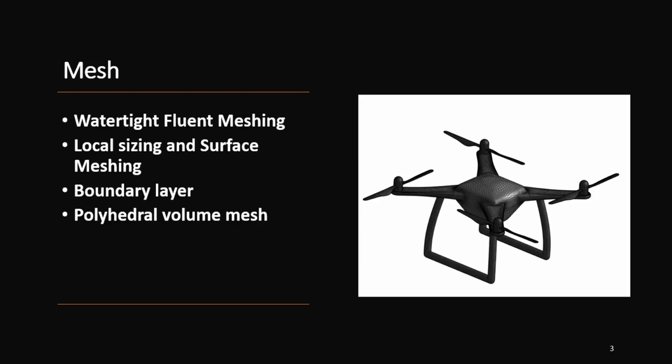You can launch Fluent Meshing in two ways. You can start from SpaceClaim, which we covered in the previous part of the video series, or you can launch Fluent Meshing in a standalone mode. To launch Fluent Meshing in a standalone mode, similar to SpaceClaim, you can go to the Start menu in Windows machines and search for Fluent and then launch in Fluent Meshing mode.